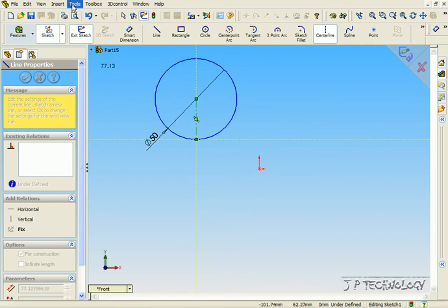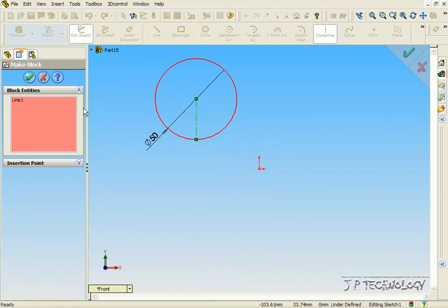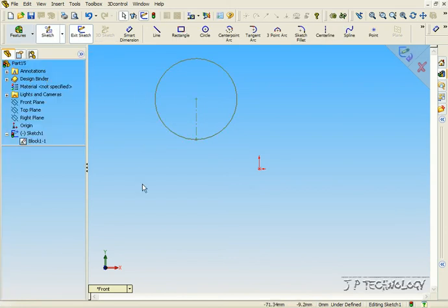And let's click Tools, Blocks, Make, and let's make our sketch block. So we already have the line selected. Now let's click the arc, click OK, and now we've made our first sketch block for our rack and pinion.